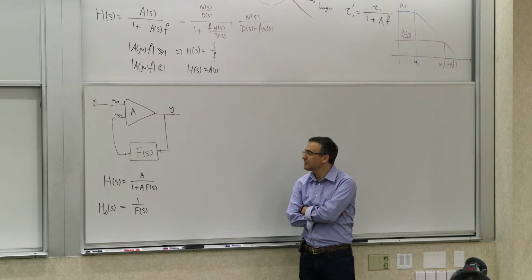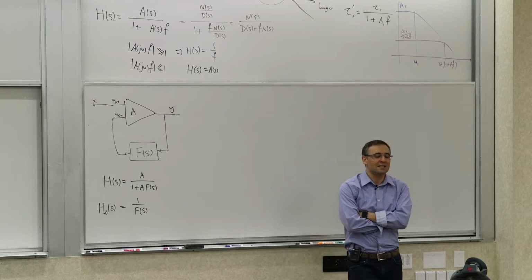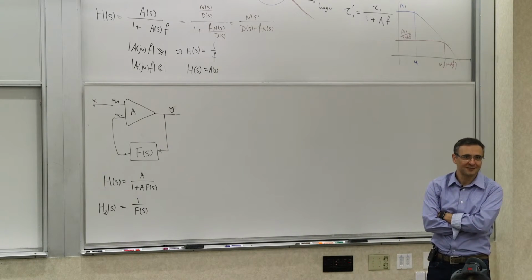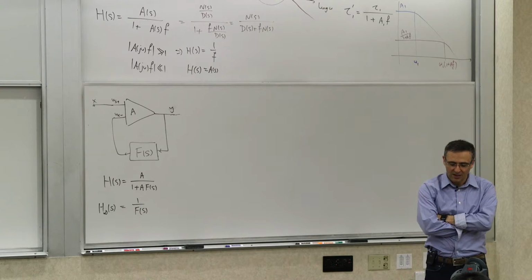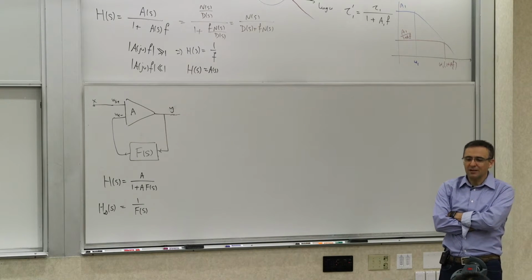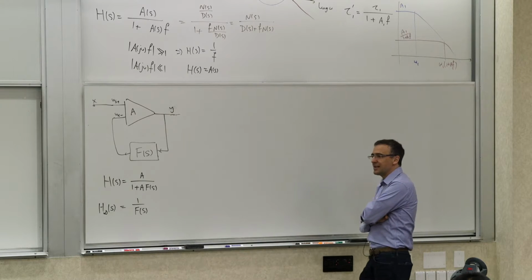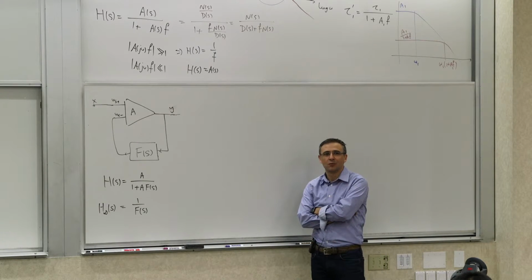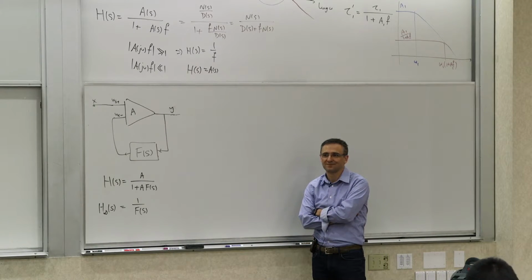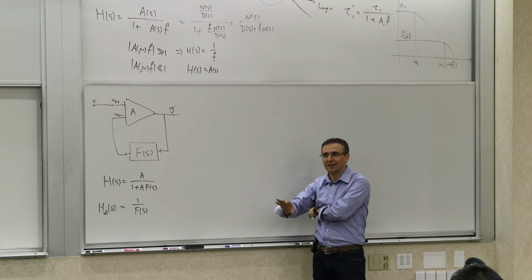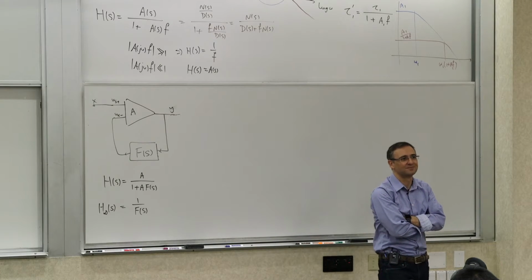You can invert that transfer function. Now, this is what we'll see over and over and over again. So this is an interesting insight. In a properly functioning feedback loop, whatever you put in the feedback path will get inverted. We'll see more examples of that, and it happens in different domains.